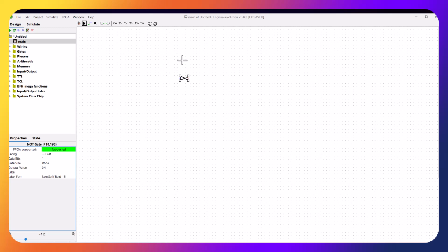All right, so here is the input, and this one, the right side, output. So I want to have some source for the input, so I'm gonna just press down with the mouse and let go. And you can see the line is in blue. This indicates that there is no power yet. And I'm gonna just press down and drag to the east, to this direction, and it forms the output, and the output is red, but that means it is indeterminate. It could be 0, could be 1, because the input is not clear yet.